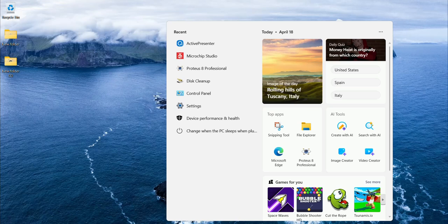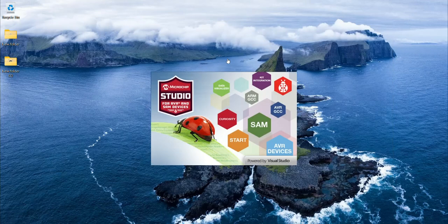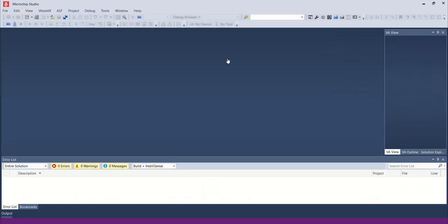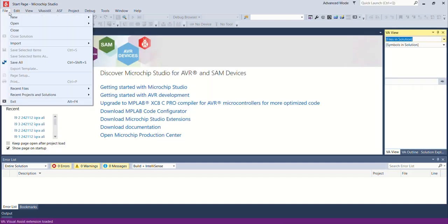Hi, today we are going to do the Lab 9 task 2, in which we are basically using Microchip Studio, AVR C language and Proteus. The task is basically to display the three interrupts on the LCD screen, and for that purpose, we are using the 4-bit or 4 ports of the LCD. Since we have 8 ports, D0 to D7, but we are going to use it for 4-bit, we will be using the 4 ports. Rest of the 4 ports are not used.